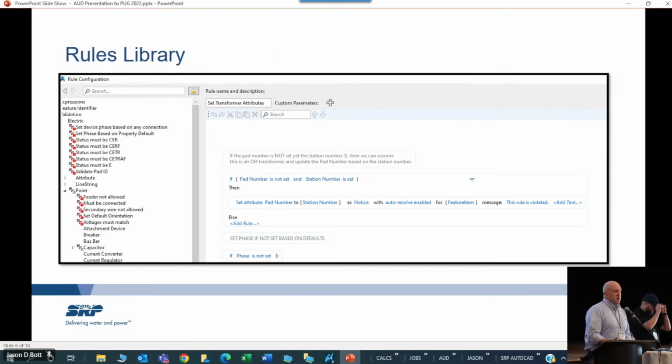If I have a situation where I'm running primary to a transformer and that transformer is fed radially, what do we do? I minus one of the termination elbows because I get two with a single phase transformer. I minus one of the termination elbows and I add in dust caps automatically, right? The designer doesn't have to go to their cheat sheet and say, oh, hey, remember to do this in these situations. Those situations that we can code or logically apply from our standards, we do so.